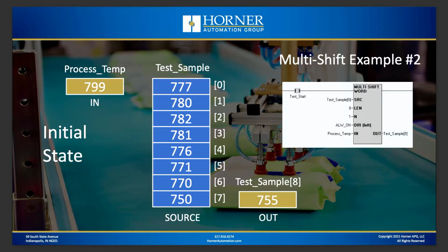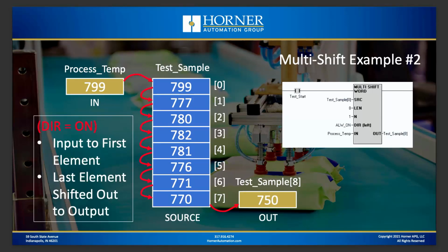It's really what you're after. In other applications, the output of the shift register is data we've already used. We don't care about it anymore. We're just discarding it. So that's one thing you'll find with shift registers. The usefulness of the output register, if you will, is going to vary based on your application. Okay, so this is what we're looking at here for our initial state. Let's go ahead and shift that left and take a look at what that means.